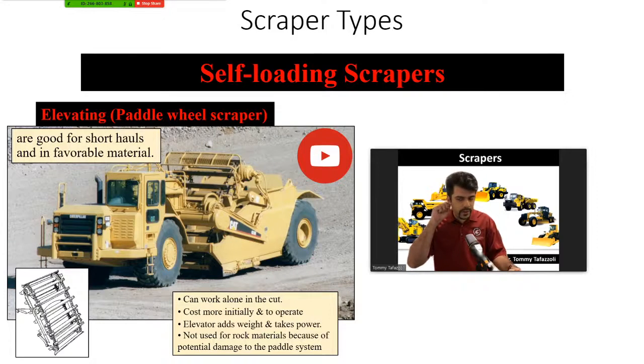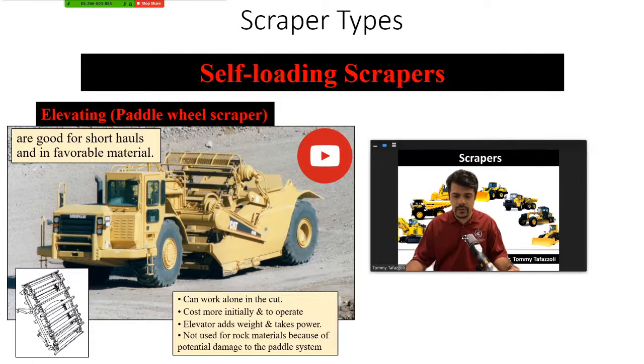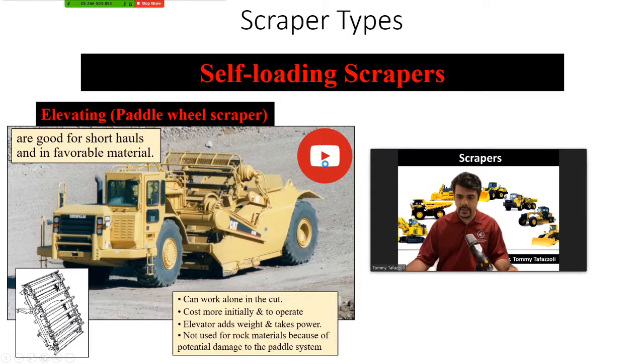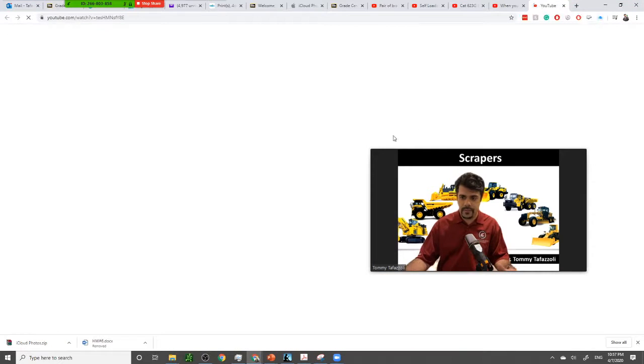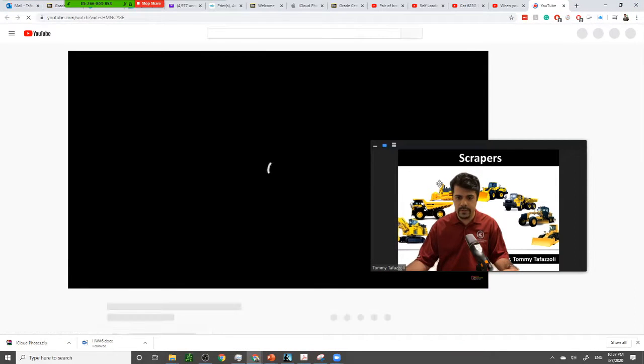So elevating scrapers are expensive. The elevator adds weight and track power, and they are not used for rock materials because of potential damage to the paddle system, and that is a general rule for other types of scrapers as well. So let's see this video about them.